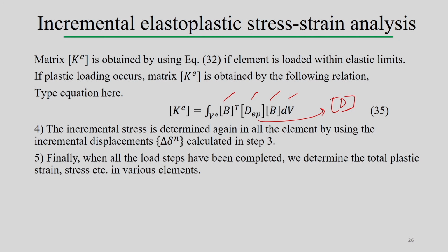In general, when you try to develop an elastoplasticity model or a thermomechanical analysis associated with the welding process, first, in stress analysis, we have to construct the stiffness matrix. Once we construct the stiffness matrix, we solve for the displacement field, and if it is incremental mode, we keep updating the displacement field. From the displacement field we can estimate the strain field, and from the strain field we can estimate the stress field. That is the usual way to do the analysis.